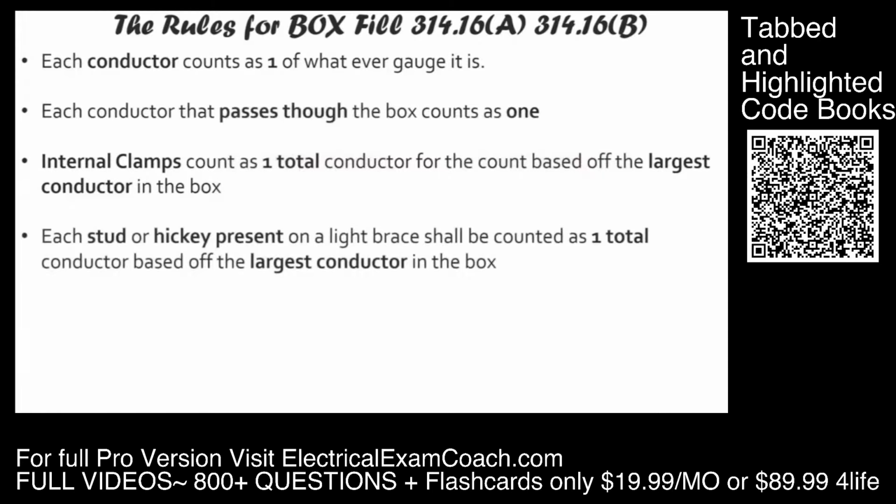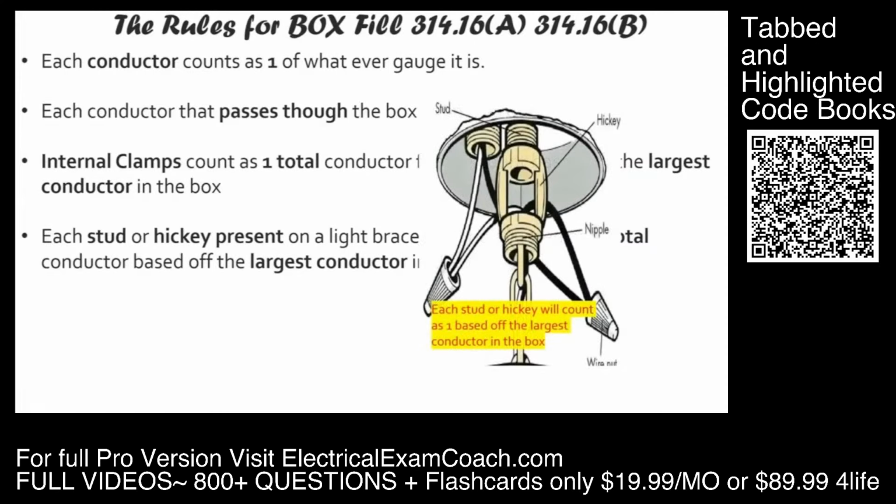Next, each stud or hickey that is present in the box shall count as 1 total based off the largest conductor that's in the box. Now, these are really old words, probably from the 30s if I had to imagine, but they still use them on examinations today. And this is what we're talking about. Imagine that we're hanging a chandelier. This we would call the nipple. But they're calling this the stud and this a hickey. And they still use this terminology on exams today, so you definitely need to understand.